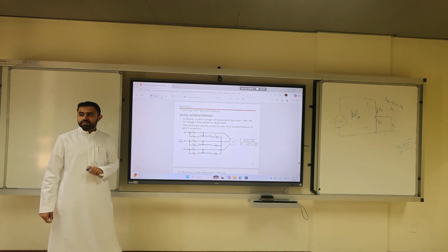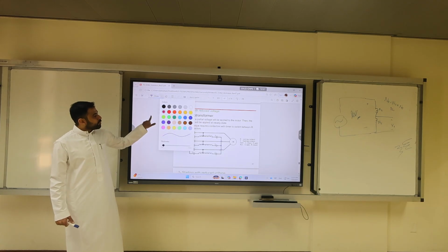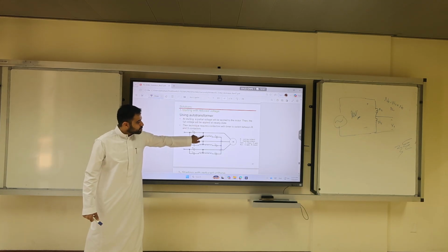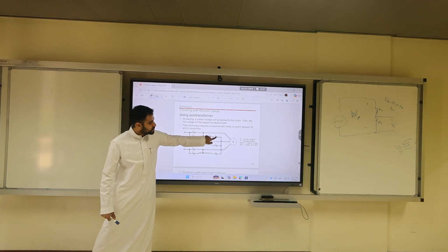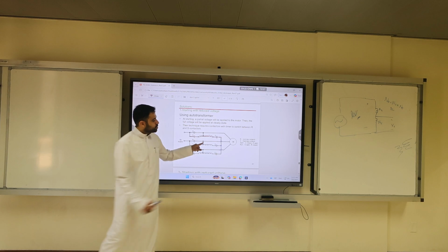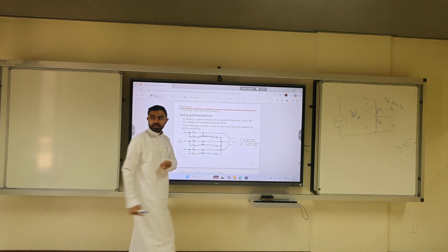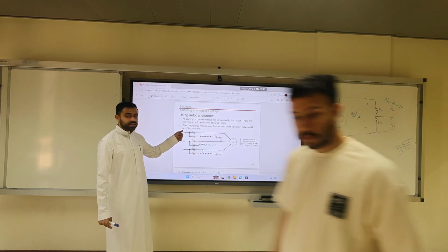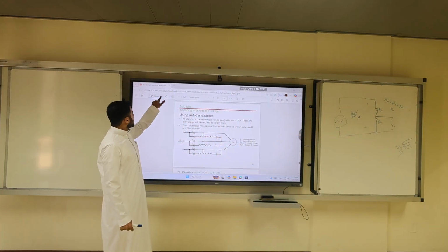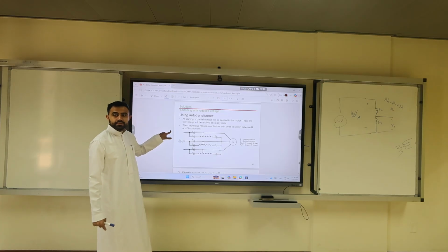The goal is that at the beginning we apply a low voltage, then when it reaches running, we connect the whole supply. Okay. Good. So the low voltage is the voltage across this coil at start. So you get your supply voltage here. Clear? You connect the auto transformer as supply. At run, remove the auto transformer. No need. Ignore them. You directly connect as supply.